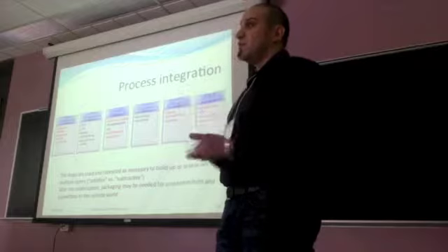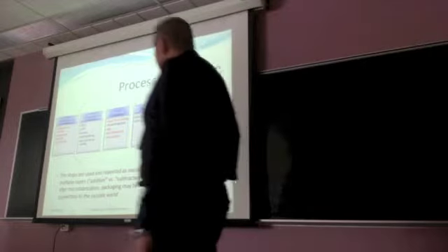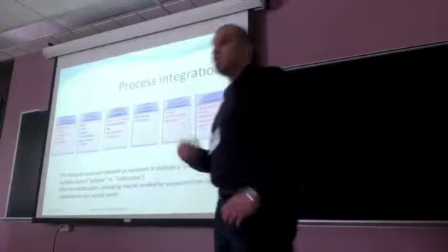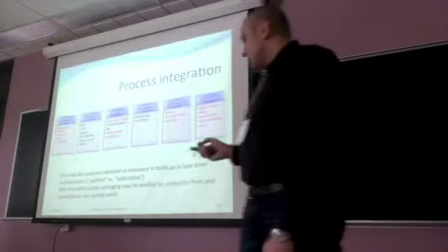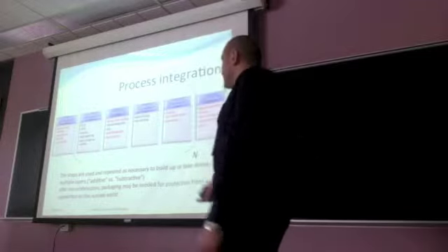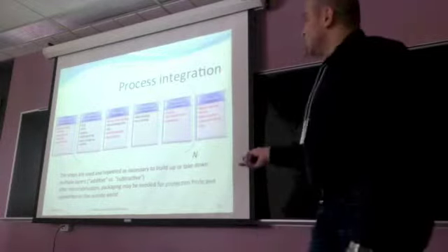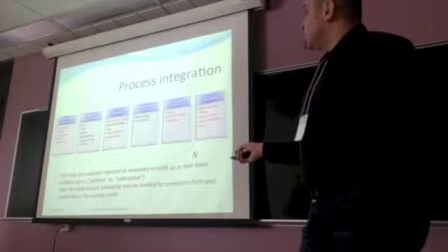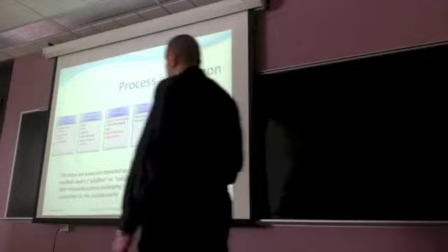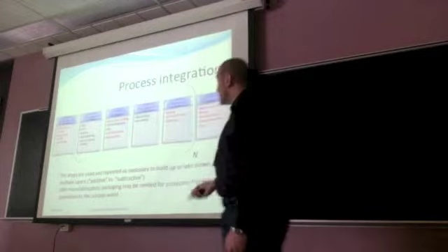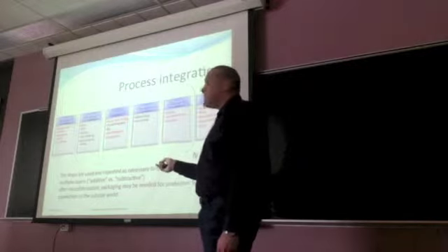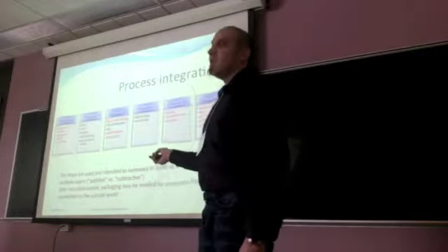So as I told you in this presentation, we can add materials to add more functionalities on the substrate. So we have different techniques: PVD, CVD, epitaxy, electroplating, spin and spray coating. We can define patterns on the substrate with photolithography and e-beam lithography, but we have also direct laser writing. So this technique is used to write photomasks. And you can write directly on the wafer if you want also.